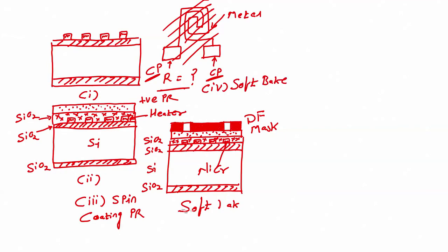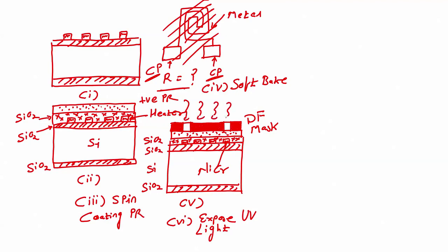Step number 5 would be load the mask. Steps number 5 and 6 would be load the mask and expose with UV light. So, now I expose this one with UV light.